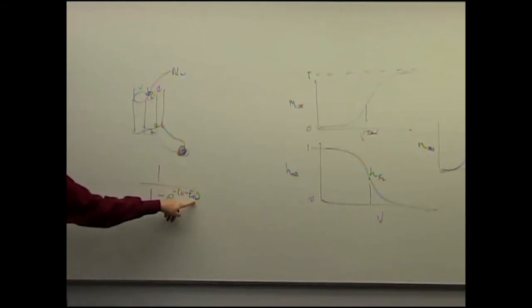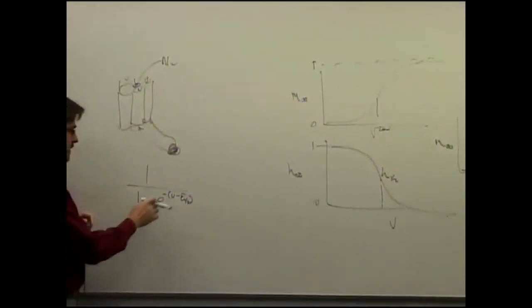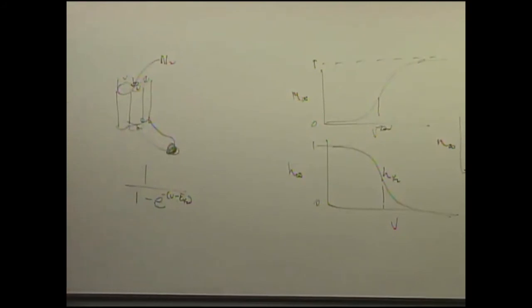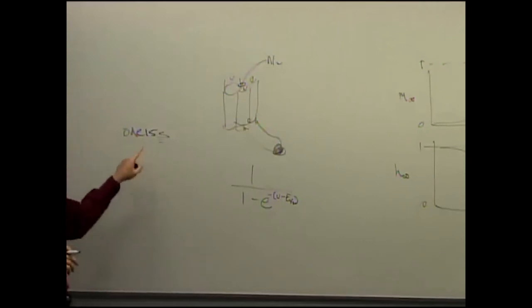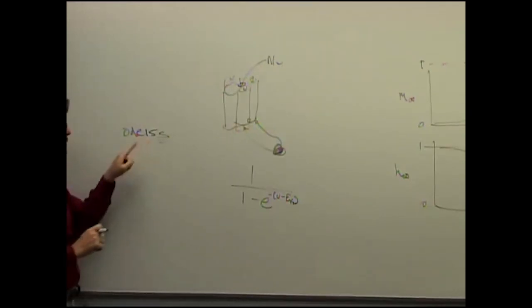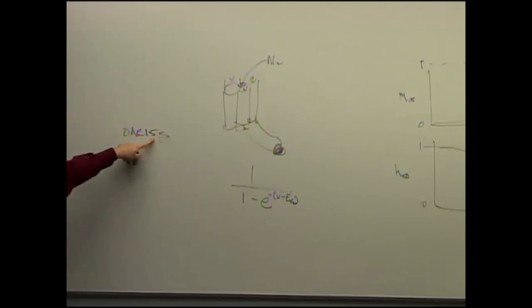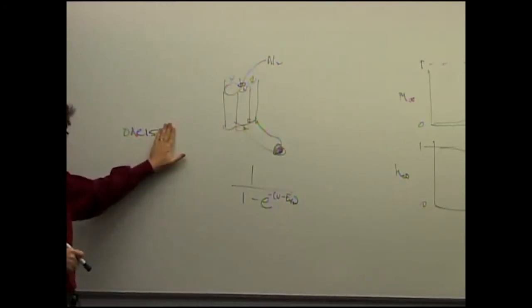And these singularities are a real problem when you're running numerical integration. Things are going along fine, and then suddenly you get a voltage which comes in here, and you get an infinity, and your equations blow up. And so MATLAB's ODE15S is for a stiff solver, and it looks for singularities in the equations. If it hits a singularity, it steps around it a little bit to solve around those singularities. So either use ODE15S, which is just fine for the Hodgkin Huxleys and everything we're going to need. If you need more precision, there's ODE23S as well. But if you use ODE45, it will crash.